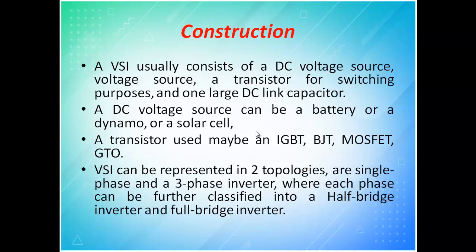When you design an inverter for agriculture, obviously you will go for three phase, because there will be a three phase induction motor. Single phase and three phase can be further classified. In single phase we have half bridge and full bridge. In three phase we don't have half bridge and full bridge, it is only full bridge.